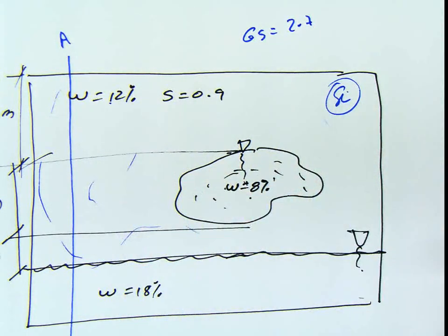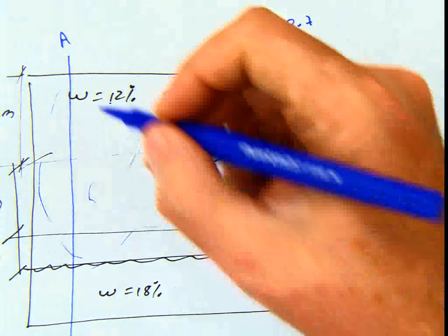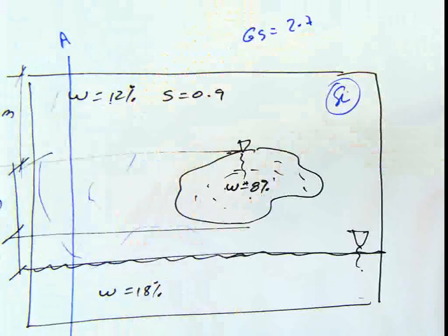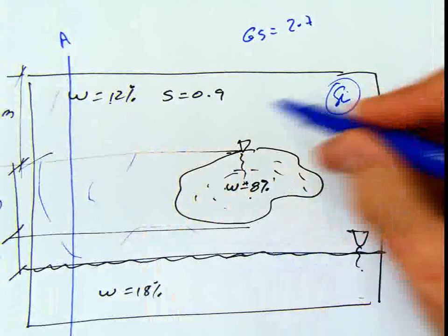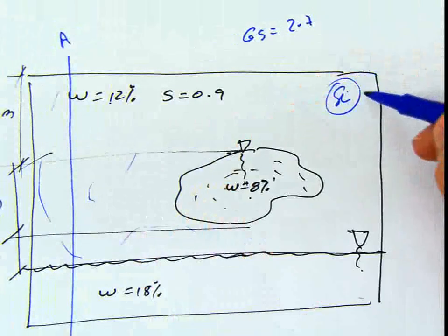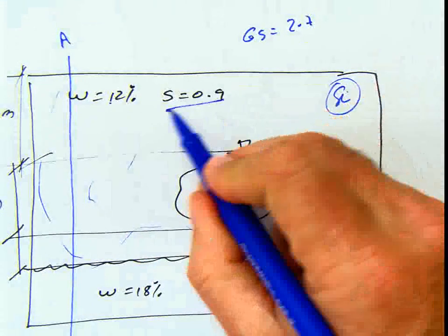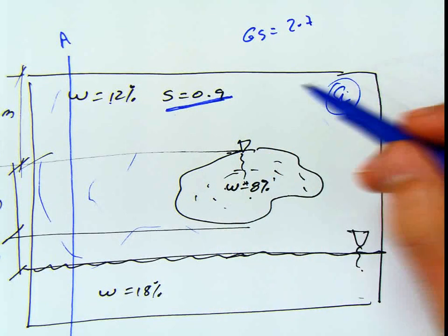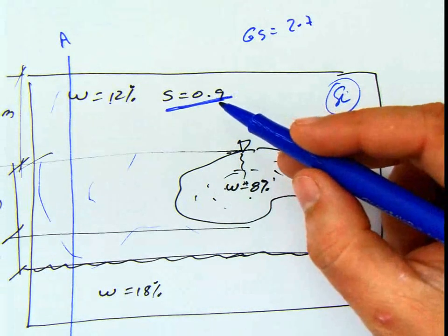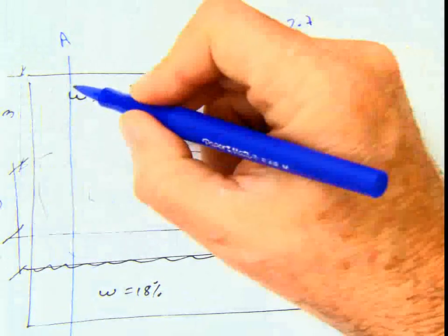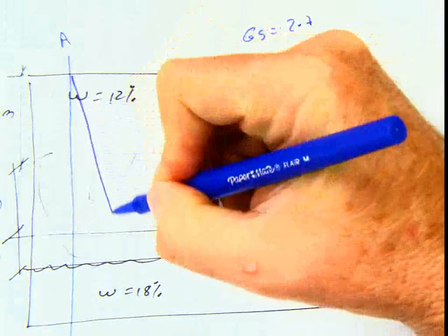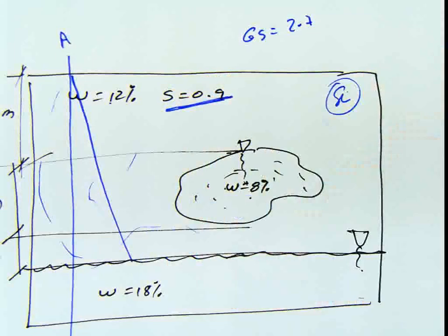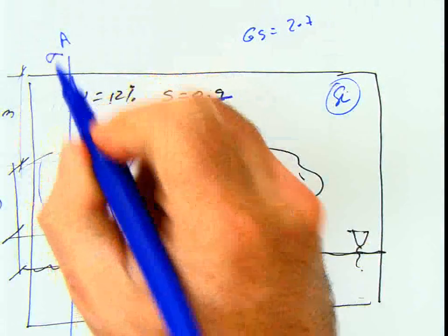Once you have that gamma, the only thing that you have to do is calculate your pressure. Everything here is moist sand, but there's no water. This doesn't mean that I have pore water pressure. In order for this to have pore water pressure, it has to be submerged. So basically, what I have is this for my total stress.